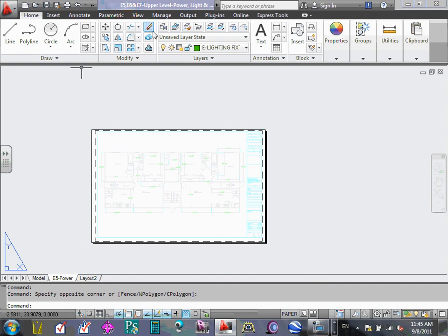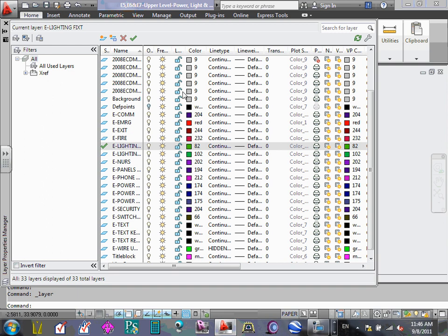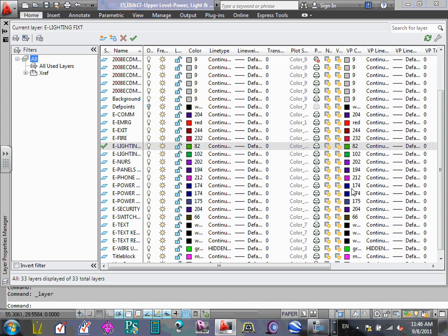Okay, let's go to the layers. Can you go to the layer manager right here and see if it's turned on? And is it an unprintable layer? Maybe that's what the issue is. Does it have this symbol in it? That should be the title block. So unclick that one. That's why. Should I do viewport also? No, the viewport should be unprintable. Okay, that's why. So the plot title block.